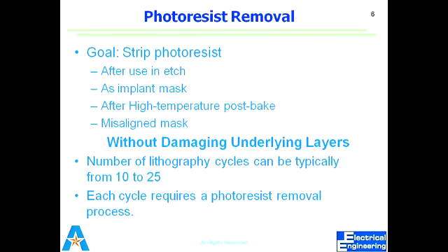For example, lift off process can be done only for the metallic layers. If I need to pattern a metallic layer, I can go either of these two choices. But if I want to pattern an elastic layer or polymeric layer, or that is not metallic, in that case, this lift off process cannot be used.